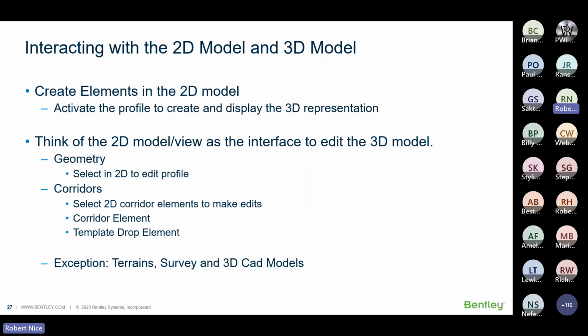Now I can still select stuff in the 3D model, bizarrely, not bizarrely, but I can pick points off there if I'm doing a corridor, for instance. So with a new design, I've got a bridge and I want to find out the elevation or pick a point across there, I can actually use that. But the 2D is the view, and you obviously get a 2D plan view, and then we have a profile view, which we'd look at our profile along section.